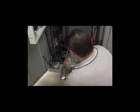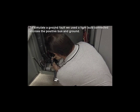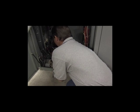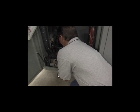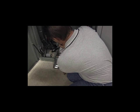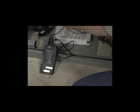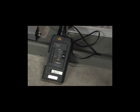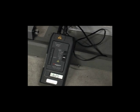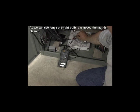To simulate a ground fault, we used a light bulb connected across the positive bus and ground. As we can see, once the light bulb is removed, the fault is cleared.